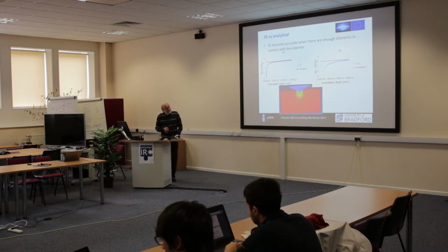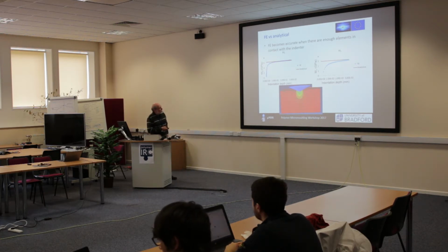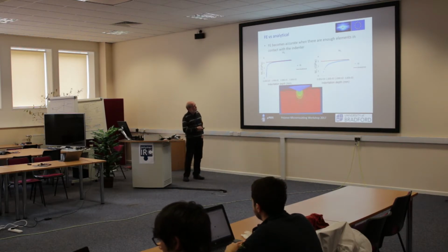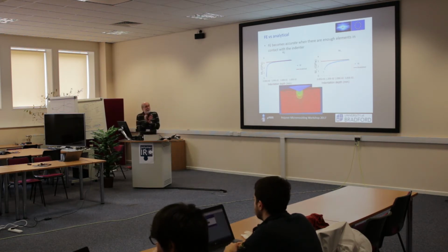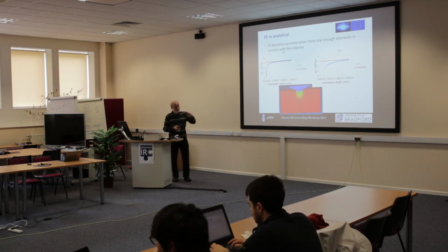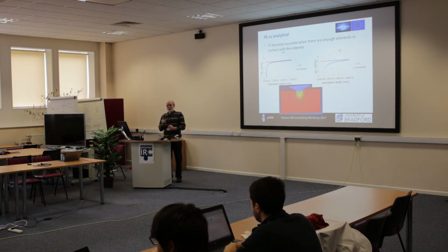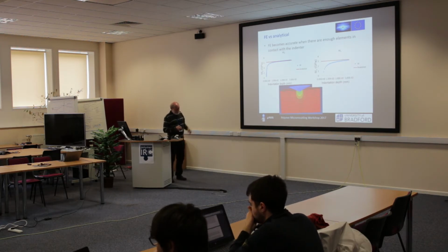So what's happening is that this analysis improves in the sense that we get better values of contact area the more we push the indenter in. You can imagine at the start of this process, we've got the sharp indenter, one node at the end pushing against another node on the surface. So that's not really much of a contact problem. It's one node pushing against another. We don't really have any geometrical effects from the indenter, so it's not really a contact problem.